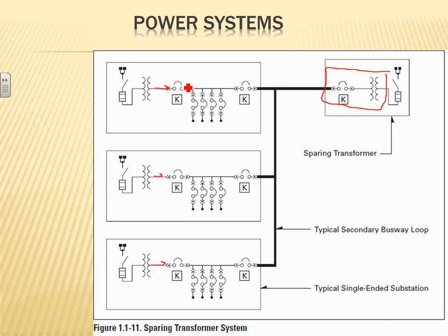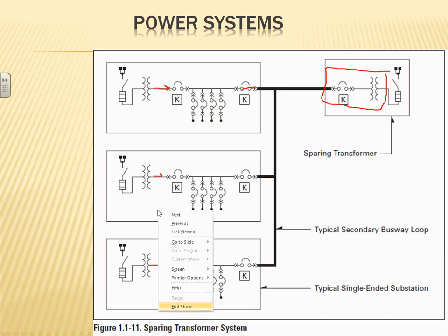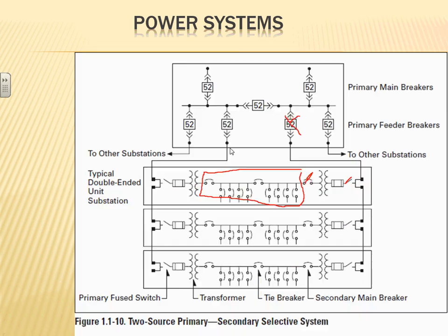Upon the loss of any of these substations, you can close to one transformer, cheaper, right? To feed any one of these, like N+1. This is very similar to N+1. So you need 3 transformers to feed your building. You put a 4th transformer. So if any one of these transformers fails, one at a time, the other transformer will take over. It's a cheaper design than the one before, which is this one. You can see how each one of them has a transformer here.